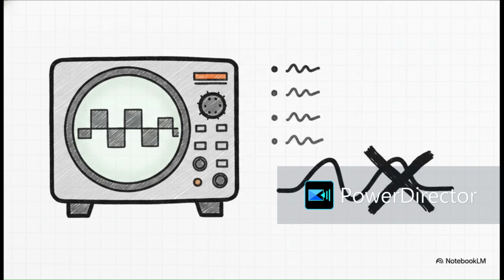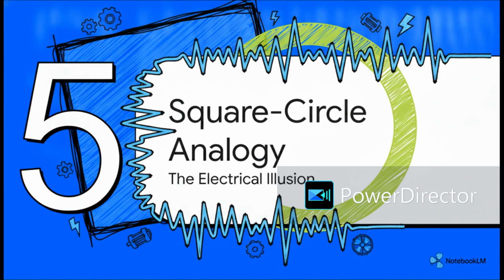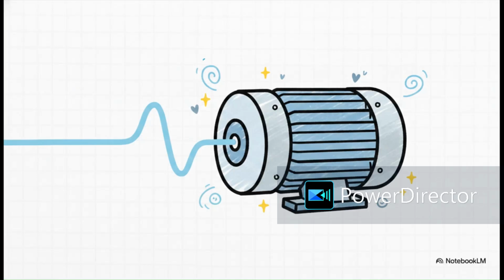But to truly show you know your stuff, you absolutely must point out one final crucial detail. A VFD using PWM does not output a pure sine wave. And this leads us to the ultimate way to close out your answer. You want to first establish the fundamental problem for the interviewer. An AC induction motor is inherently designed to operate on a pure, perfectly smooth alternating current sine wave. That's what it wants to run smoothly, keep cool, and operate efficiently.